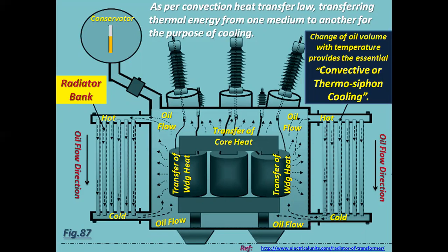As per the convection heat transfer law, thermal energy is transferred from one medium to another for the purpose of cooling. See the diagram. This is the radiator banks. Transfer of winding heat, transfer of core heat, transfer of winding heat, oil flow. Change of oil volume with temperature provides the essential convective or thermosiphon cooling.